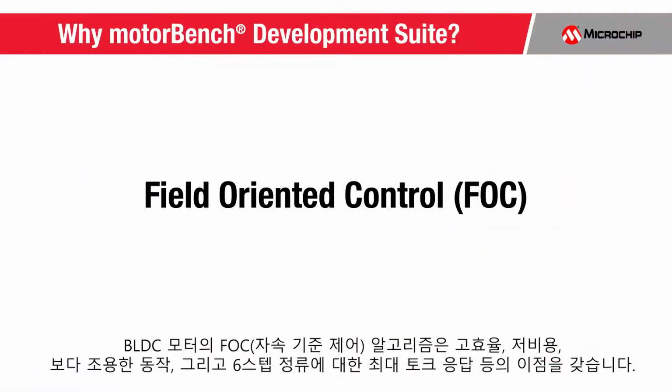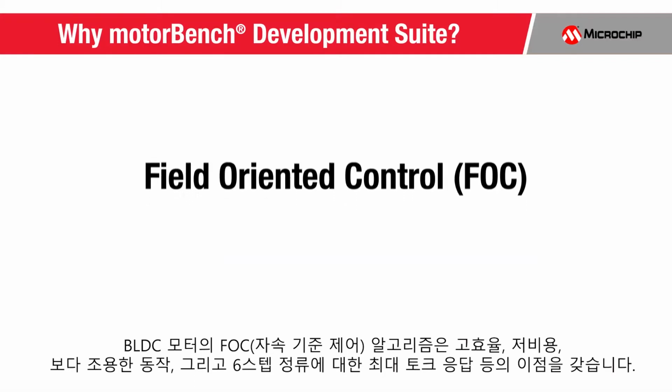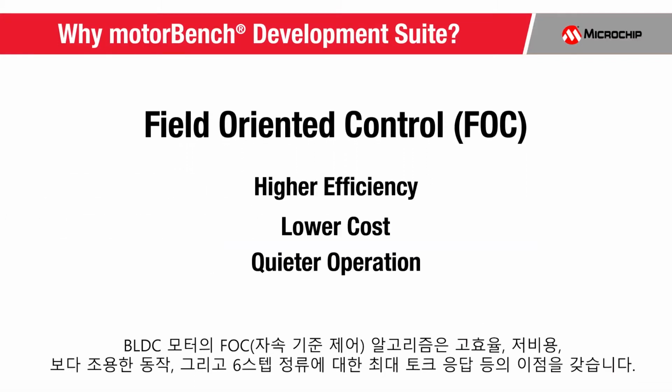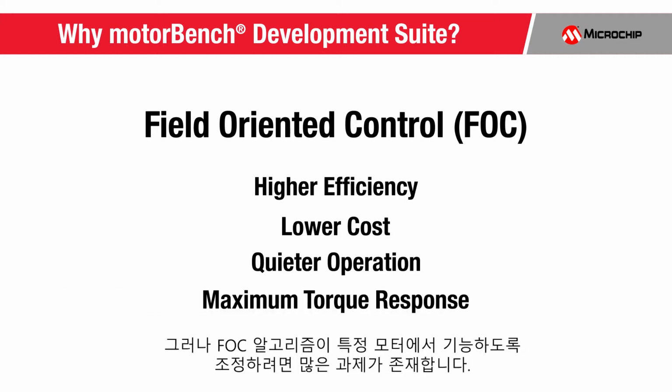The Field-Oriented Control Algorithm, or FOC for short, for BLDC motors provides the advantages of higher efficiency, lower cost, quieter operation, and maximum torque response over a 6-step commutation. However, there are many challenges to tune the FOC algorithm to work with a particular motor.